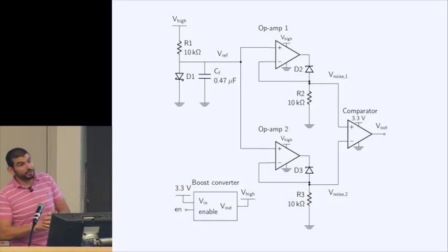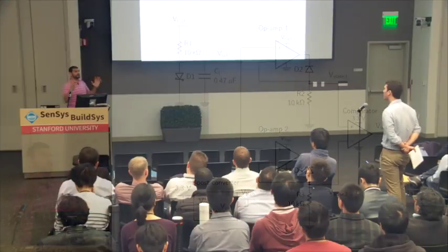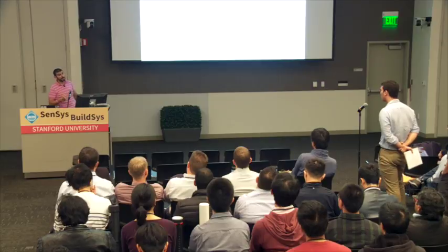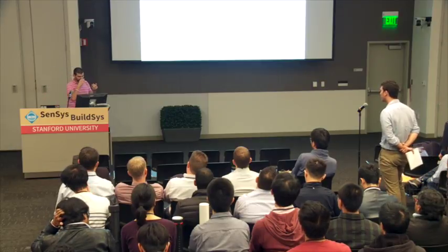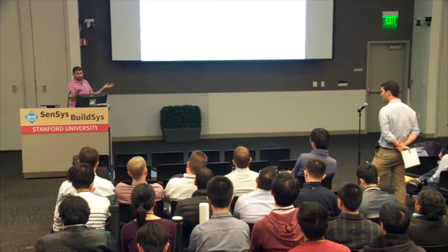So it's really the high frequency noise that is being detected by the comparator here. There are a couple of solutions. One, a higher bandwidth comparator, and life is okay. Two, which I think I've already mentioned, adding an integrator to this feedback loop. It makes the circuit diagram more complicated, but it's exactly the same. We're simultaneously killing any imperfection from low frequency gain issues, and we're killing the bandwidth of the op-amp, so that averaging out to the gain bandwidth becomes averaging out to say 10 hertz or something.